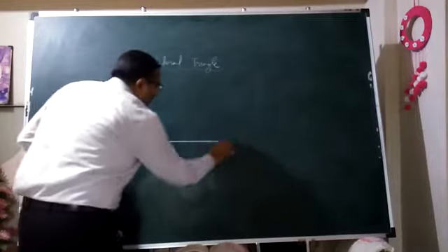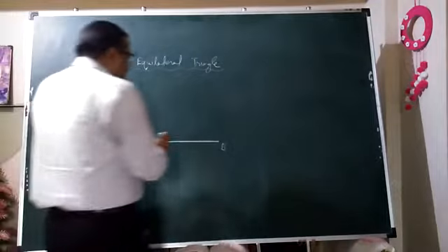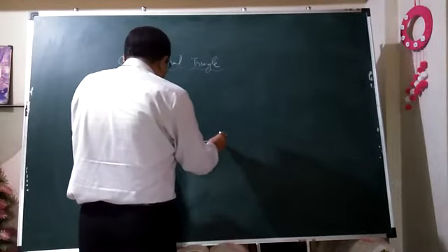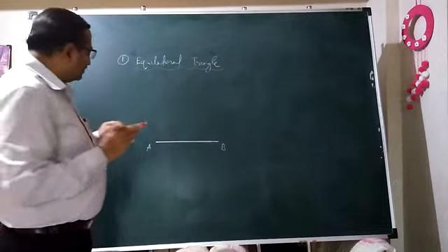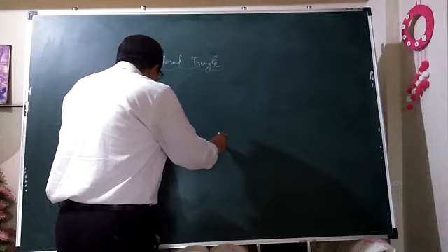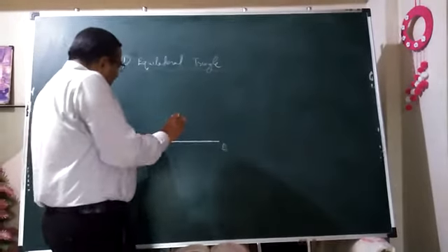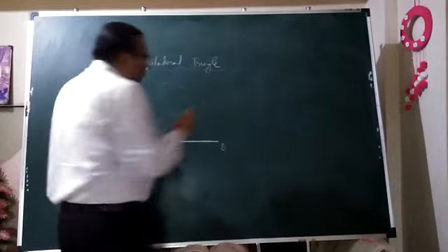So first of all, I have drawn AB as the 50 mm long segment. Pick the same distance of 50 mm from the line itself. Don't use a scale, not at all. Okay, it's not required. Now with A as the center and this 50 mm as the radius, draw one long arc above this line in the space in this way.